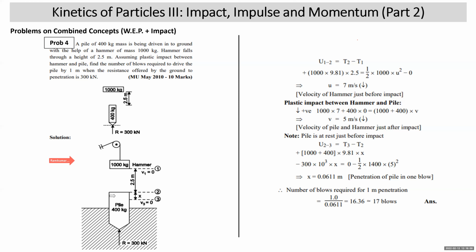In the pile foundation, the area where the building or bridge is to be constructed is not excavated completely. The pillars, which we call piles, have a conical shoe at the bottom, as you can see over here. Number of such piles are erected into the ground without excavating the ground.